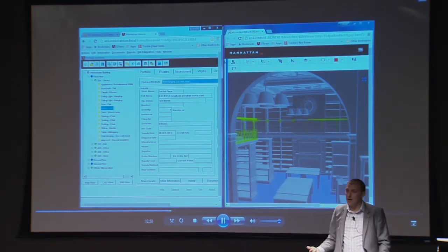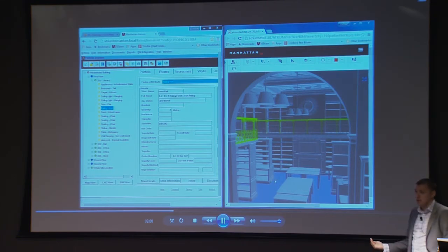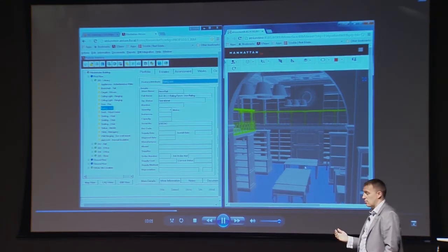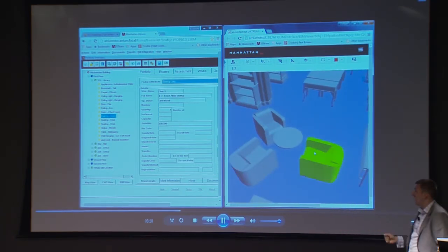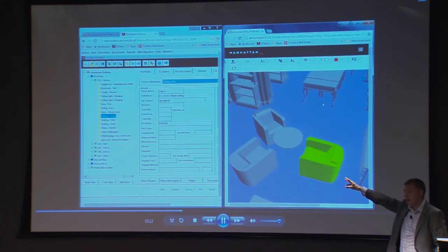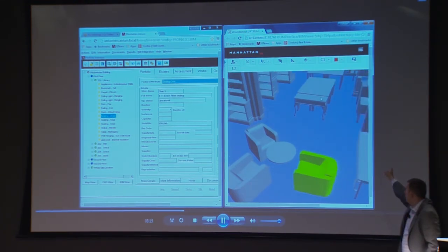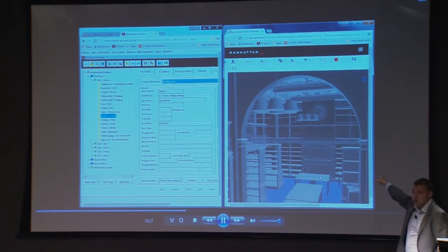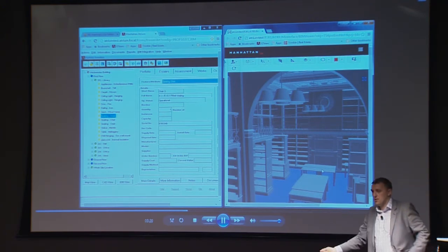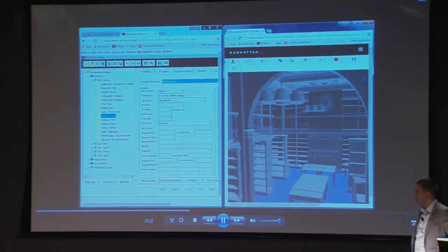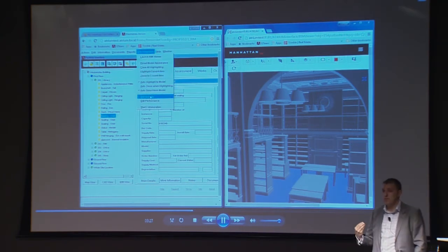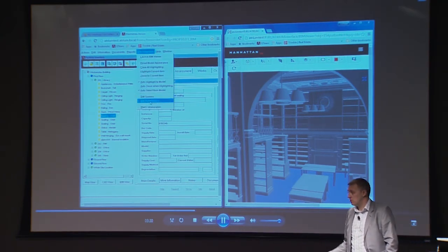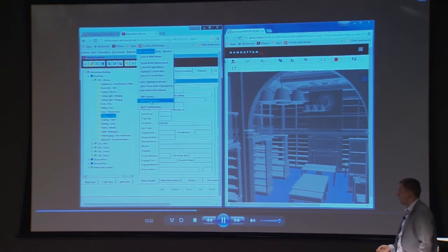Now you'll notice in there that we've got some core details that come up, so we can very quickly see the serial number, make, model, manufacturer. There's warranty information as well if we want to view that, so I can make sure that I'm always maintaining the assets within the relevant warranty. But I could also go and view the previous work history, everything like that. And I can either do that by looking at that within the Atrium application, or I can pull it up in the properties screen, which is on the right-hand side of the BIM window here. But you just need to set up what data is relevant for you, because as Bill highlighted, it's all about getting the relevant pieces of information out to the individuals who are out on site.